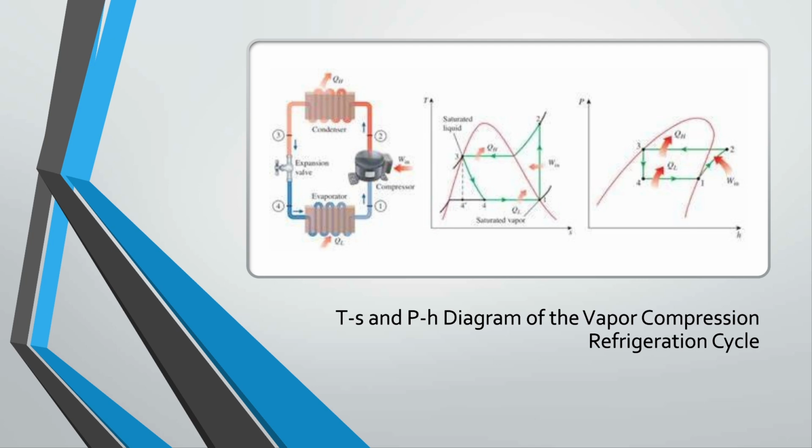As heat is absorbed, the refrigerant evaporates, moving across the graph toward higher entropy. Then, in the compression stage, the refrigerant's temperature rises sharply as it is pressurized by the screw compressor, which is shown by the steep upward line. Next, in the condenser, the refrigerant releases heat to the surroundings, which brings the temperature down while maintaining high entropy. Finally, it passes through the expansion valve, rapidly dropping in both temperature and pressure, and returns to the evaporator to